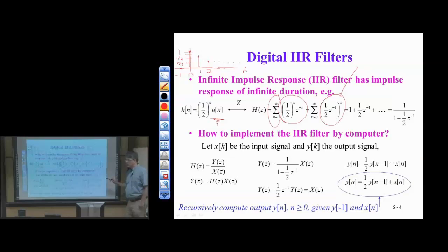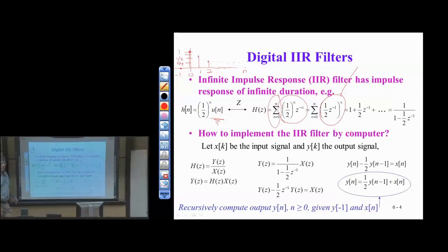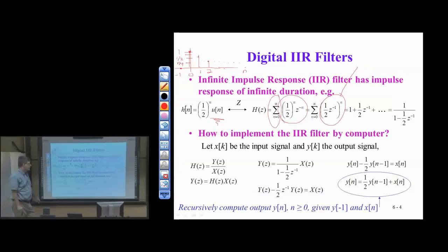Now, this also leads to the region of convergence. We can multiply both sides of the inequality by the absolute value of z, provided z is not 0, and we can get the region of convergence. So this means that the absolute value of z is greater than 1/2. This is the area of the z-transform, or the z-domain, that's outside of a circle of radius 1/2.